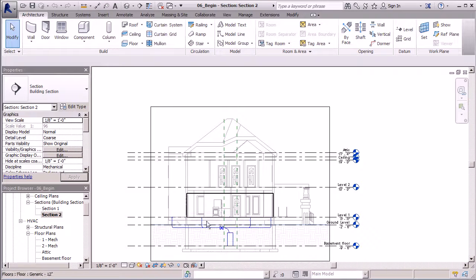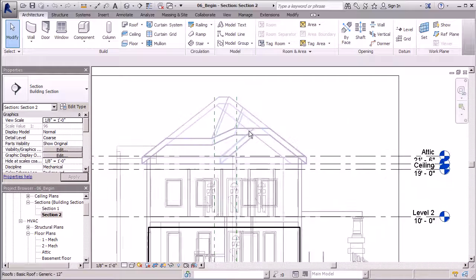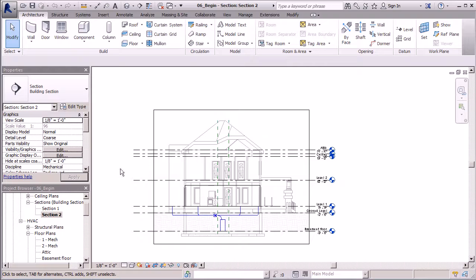So we have our ground floor system in place that's located in the basement, and it feeds our ground floor through ducts that feed through the floor. So we're gonna take a little different approach this time. We're gonna go from the top down in this lesson here. We're going to have our air handler unit placed in the attic, and we're going to feed air through the ducts, and they'll hit these air terminals that are located on the ceiling. So let's begin by placing out our equipment again.